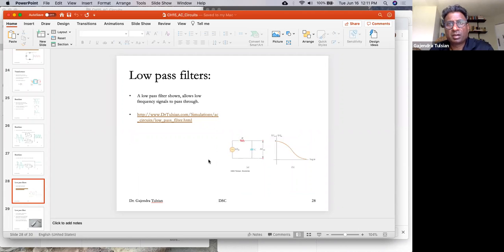So on the wires, you get many frequencies coming in, and you feed those frequencies, and at high frequencies, the resistance of this goes down, so you don't get any output voltage. Okay, so with a circuit like this, if you're looking at the voltage out here, you can only see the low frequencies.